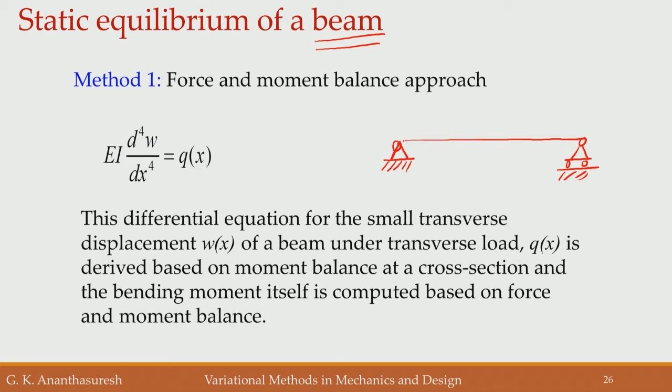So, there is a hinge. Now, if there is a force acting on it or forces, does not matter, any number of forces, it is going to deform in some way, right. So, now we call this function W of x, transverse displacement, where x goes from 0 to L. Let us say this total length is L.